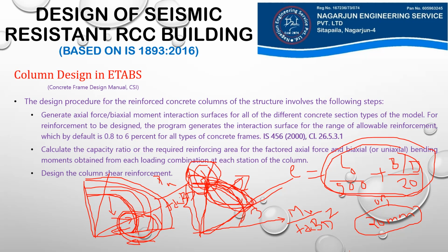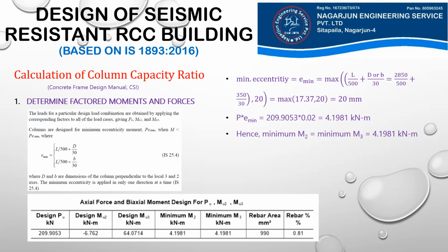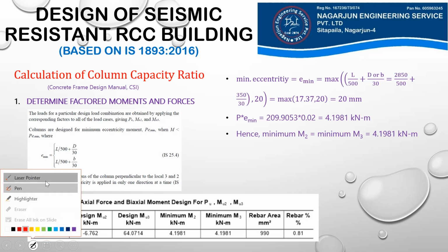And from these curves itself, if the reinforcement in a column is to be designed, then we determine the value of reinforcement required to resist that amount of axial load and bending moment. So this is the concept of interaction curve. So let us go through step by step for the design of columns.